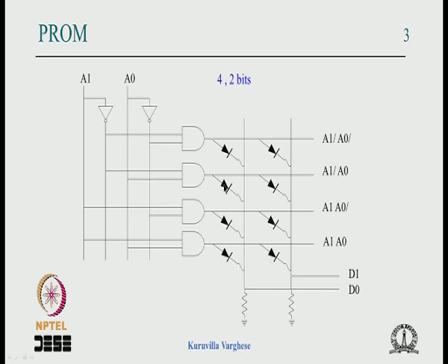And as I said, when you program 1 and 1 in these two locations, and when you give 0 1, this will be 1 and this output will be 0 because only one min term will be high. Then if there is no diode there will be a short circuit. To avoid the reverse flow, this diode is put everywhere. And the fuse itself is blown by applying a negative voltage here for a short duration that will force larger current through the fuse to blow it.